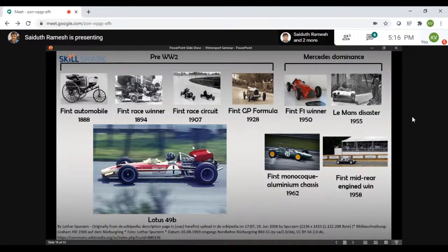Now, what aerodynamics actually does is it presses the car down onto the ground. So when you're cornering, it presses the car down, so the limit of static friction increases. So you have a longer limit for lateral loads before it starts sliding and kinetic friction comes into play. So that's where aerodynamics started showing its face in motorsport.